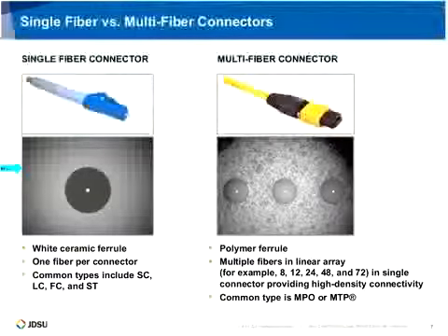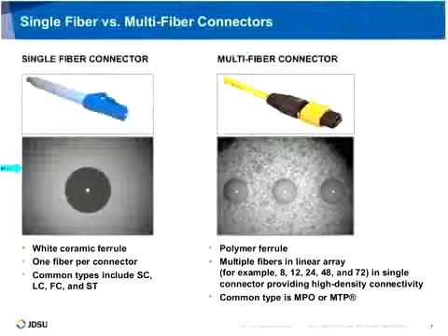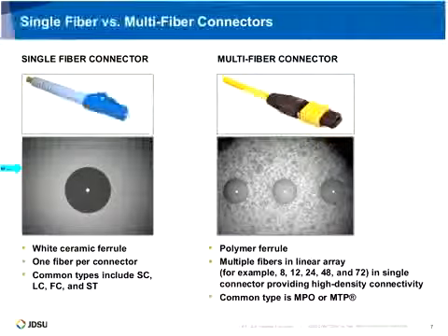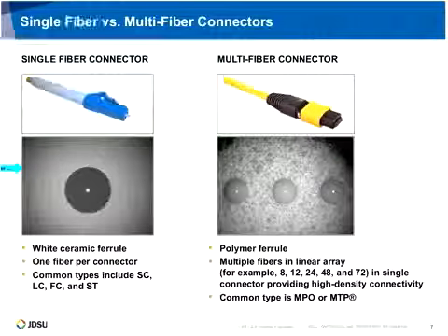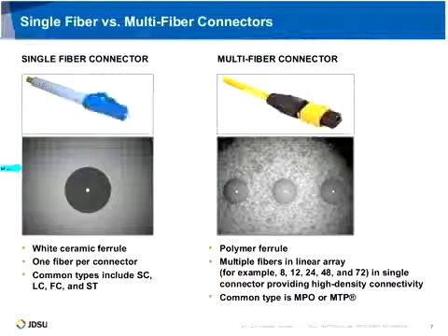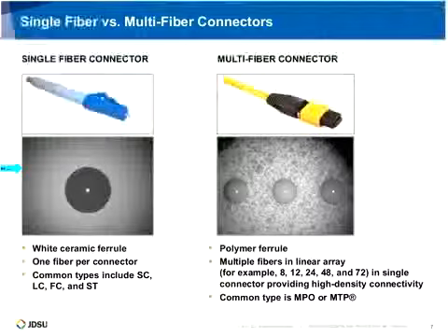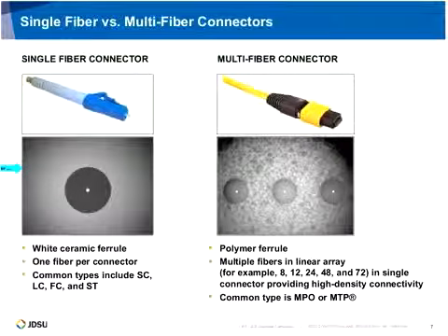These are really interesting in that they give up to 72 fibers in a single fiber connector. The amount of fibers ranges. It can be as minimal as 8, and it jumps there from 12, 24, 48, all the way up to, like I said before, 72. And they literally just lay out rows of fibers inside this ferrule. This screenshot here is just a brief snapshot showing 3 fibers in an array. That actually has, I think, about 12 in that particular array, and then there are multiple rows of 12 shown there.